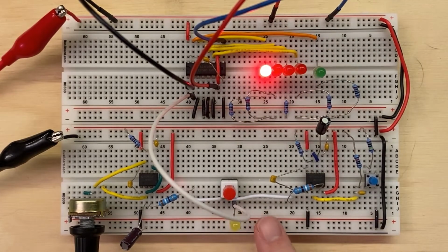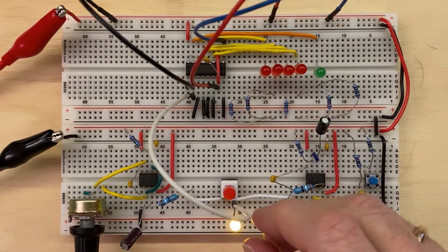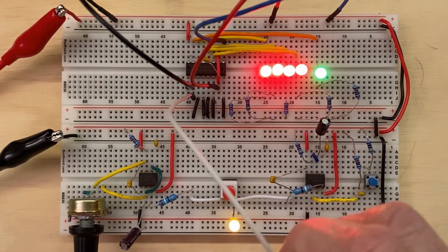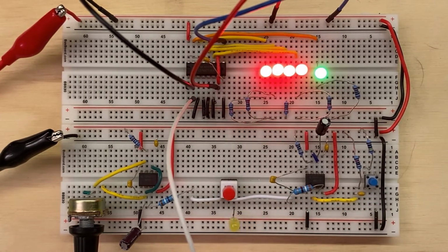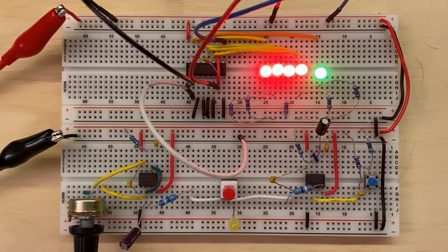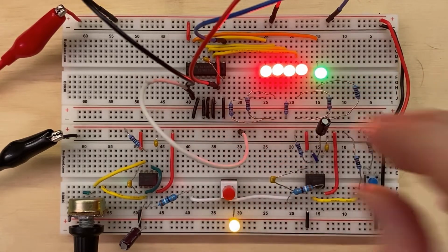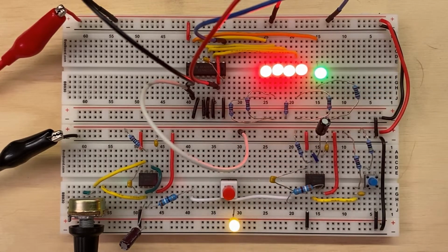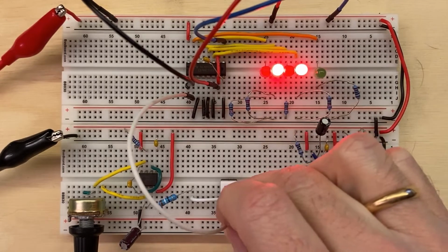And now to the clock pin, which is the most critical signal, and it's the most sensitive one. If I were to pull out the clock pin and just have it float, you see the output kind of goes haywire, and it's just doing whatever, some craziness. Now if I ground it, there's no clock, and it just doesn't do anything. If I take it out and I put it in high, on the 5 volts, it's the same thing. It stops counting, because even though it's at a positive voltage, it's at a logic 1, it's only on that positive edge that it does something. Okay.